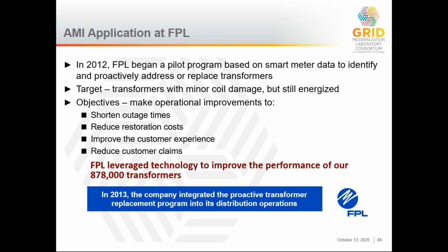So in this experiment, or in this pilot, they were essentially looking at how to proactively manage the transformer program in distribution operations by using the smart meter data, and how to monitor those voltages and determine if there's a particular problem. This was a particularly successful application where issues were identified with a particular make and model of transformer that was out there, because consistently high voltages were being read at those locations. With some fancy analytics put on top of that, you can perform some pretty advanced features.